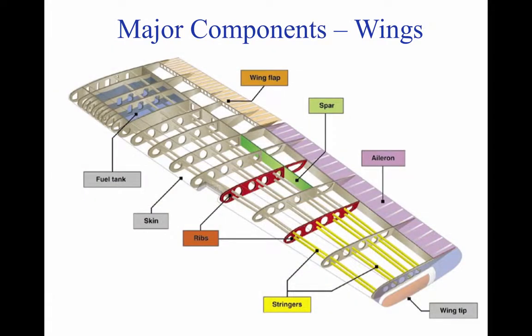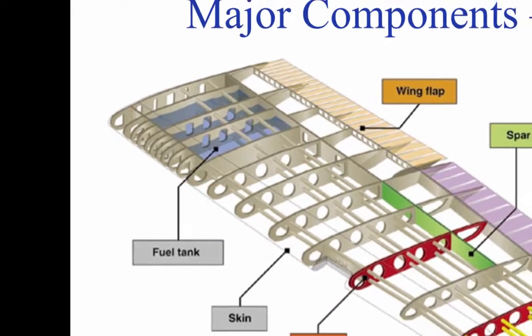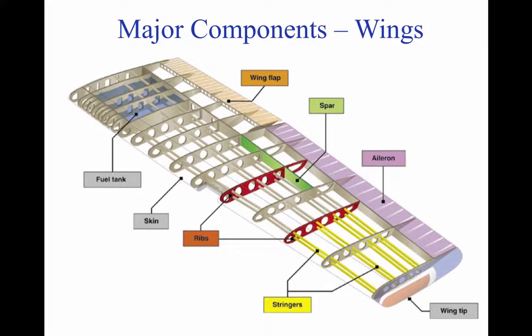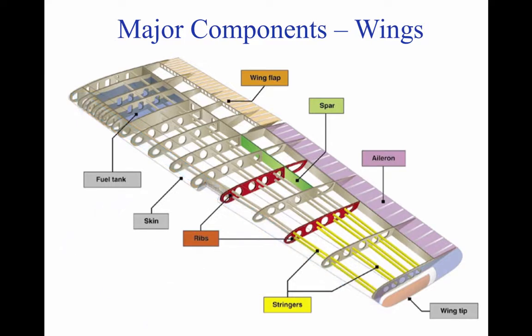The picture above shows the general construction of a modern wing. The ribs, stringers, spar, and skin all give the wing structure. The fuel tanks in most modern airplanes are also contained in the wing near the fuselage as part of the wing or in flexible containers. The front of the wing is the edge that the wind hits first, also known as the leading edge. Attached to the opposite side of the wing, or trailing edge, are 2 control surfaces called the aileron and the flap. Wings are exact mirrors of each other and contain the same control surfaces on both sides of the airplane.